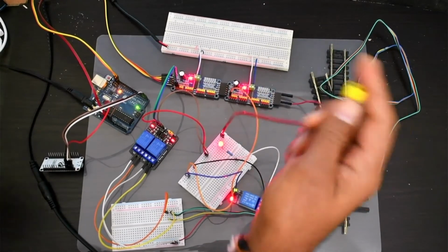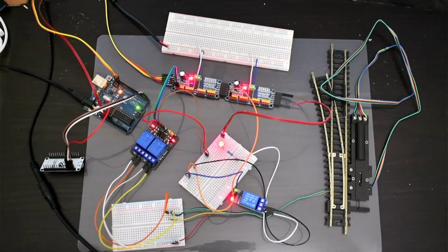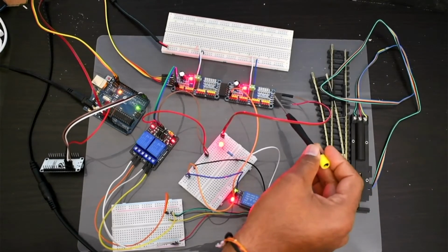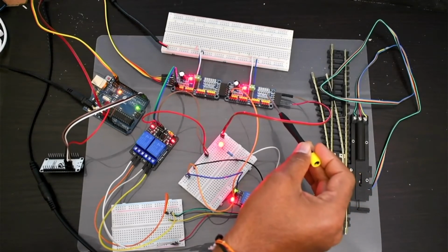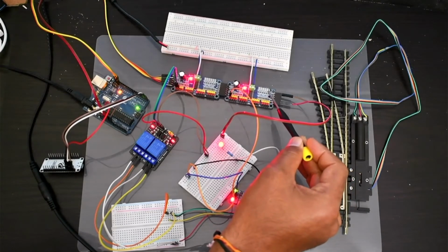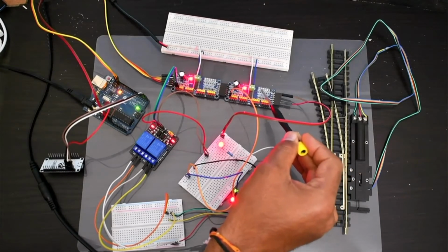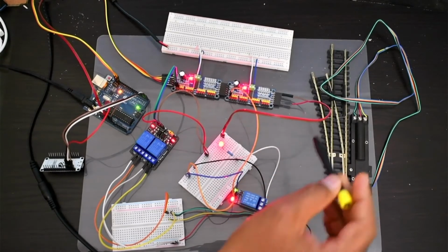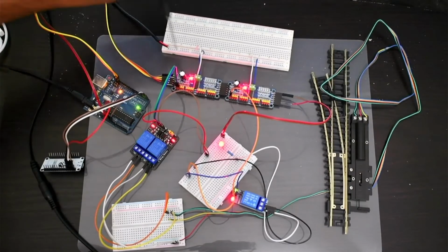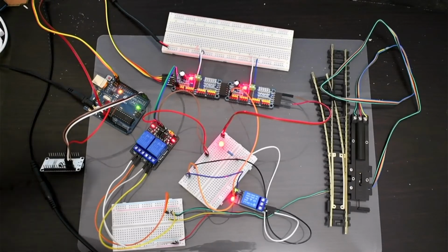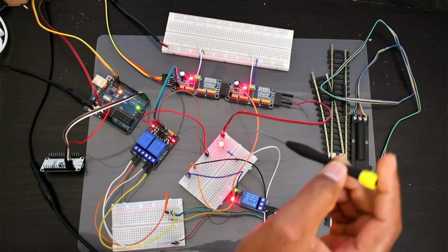so that you can snap the PCA9685 boards together. And another thing, if you have been following the video tutorial, I have already explained how we can generate a new address for the PCA9685 board. Here you can see this section is soldered. There are multiple points, and if we solder the first one, it will generate the address number 41 for us. By default this address will be 40, and this is 41. So this is how we have configured the board,